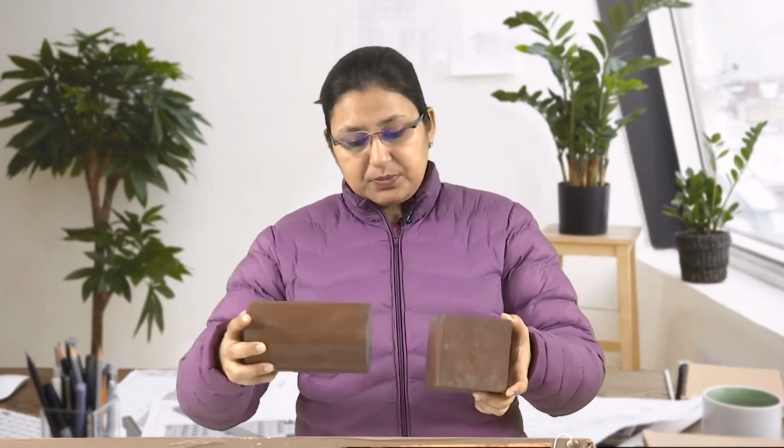Assuming that we have a rectangular prism kept like this on the ground, it is intersected by a circular cylinder perpendicular to its axis, and it will pass through it and actually be penetrating this prism. This is a very simple position. So we are going to start with that, and then further we will see how we arrive at the more complicated ones.